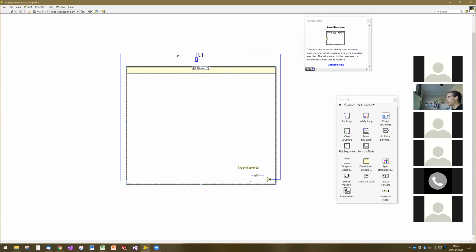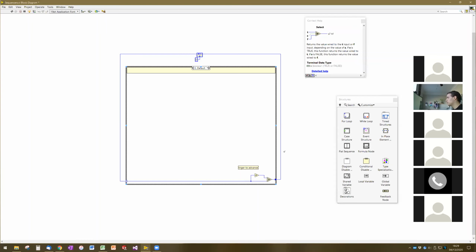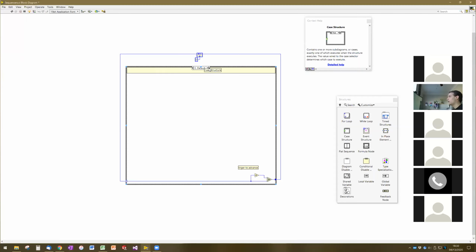So again, when we start out, we are in state 0. If our trigger is false, we stay in state 0, and so we come back around, and we're still in state 0. If our trigger is true, we're going to add 1 to 0, and so the next time we come back around, we're going to be in step 1. And then we're in step 1, and again, we're waiting for this trigger. When we're false, we stay in step 1, and then when we see that trigger again, we'll advance to step 2. Does anyone have any questions about how we advance from one step to another step inside of the sequencer?